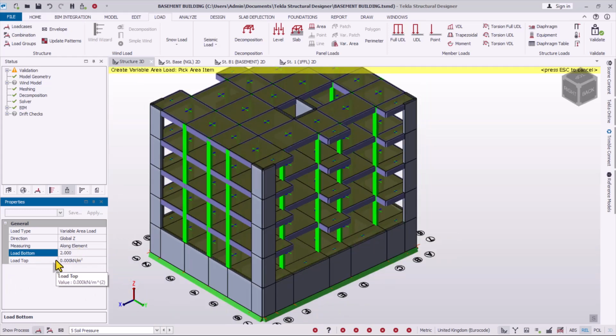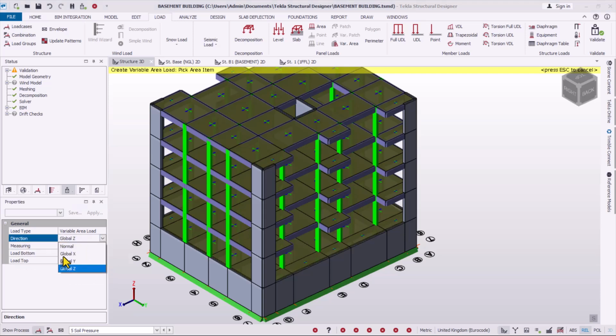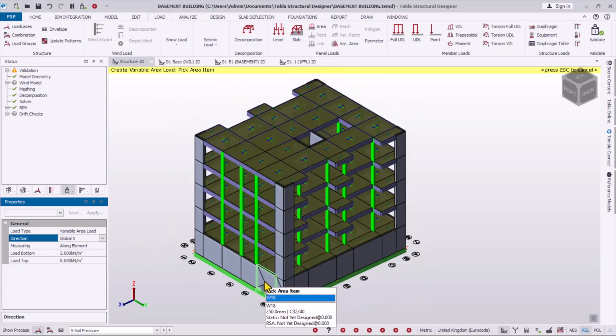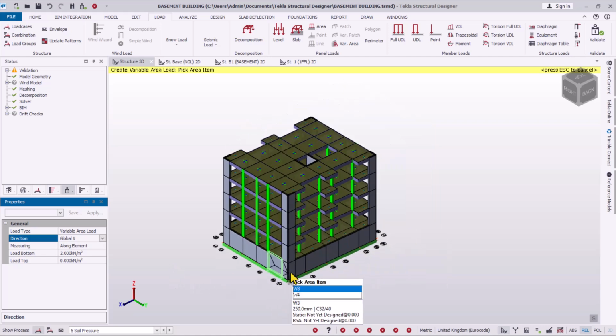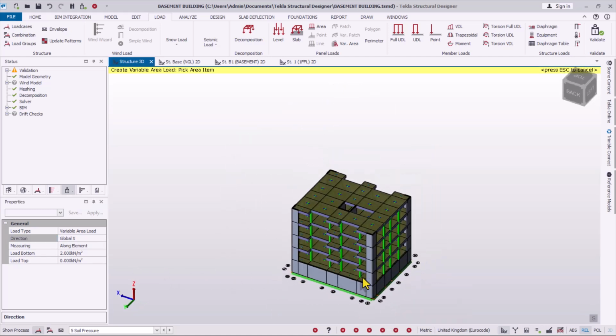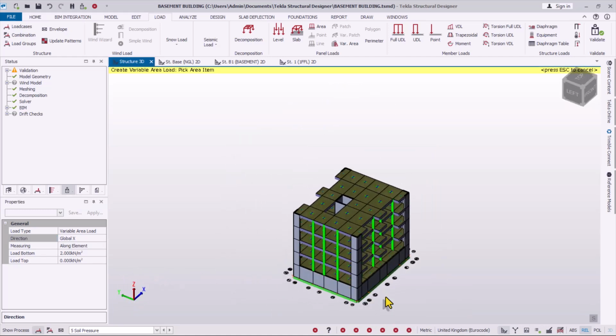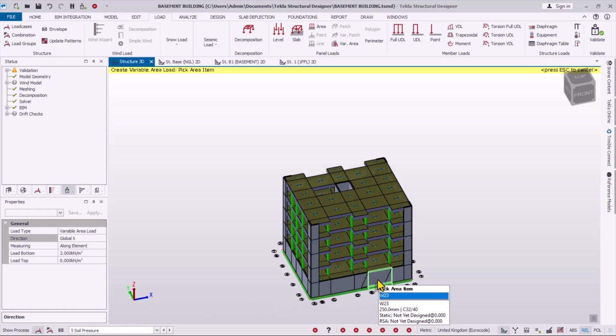So that is what this simply means. Once you have this load value applied here, you need to go to the directions and change them properly. We go first in the global X direction. When you want to place the load, you need to check the UCS icon. Just orbit the model like this to check it, so you can see the direction X is facing.